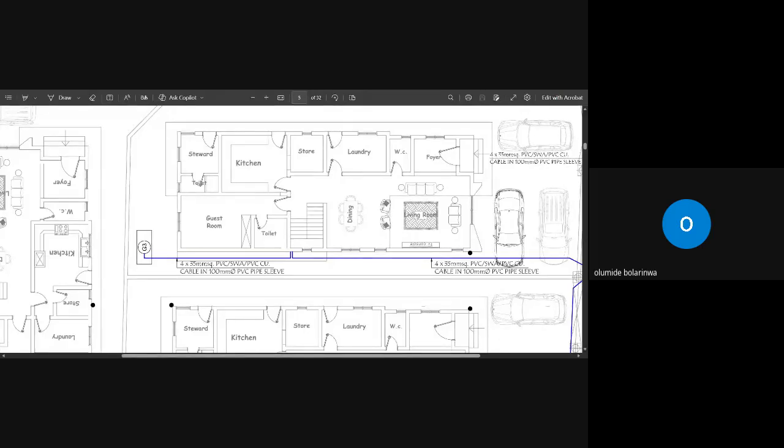Are we recording all these things? After that, the height of your changeover. Are you there with me? Remember that your changeover is beside your metering, so we allow a 1.5 meter extension to where your changeover is.